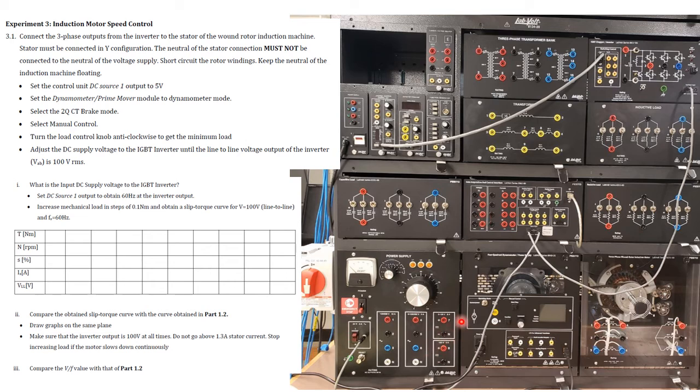When you measure the DC one, in the app you should put it on DC, and when you measure the AC one, you should put it on AC. Don't forget this. You cannot do it manually, because when you connect it to the computer, this would change.